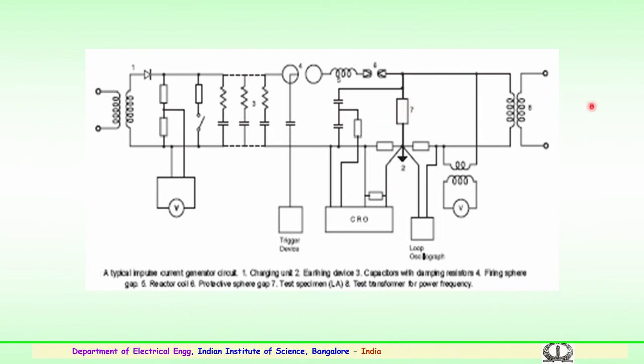The lightning arrestor is continuously supplied with AC voltage, and a suitable impulse current generator discharges impulse currents through a number of capacitors in parallel via the sphere gap mechanism, superimposing on the AC waveform while measurements are conducted. This is a typical example of surge arrestor or lightning arrestor testing in the laboratory for both the AC and the impulse currents.